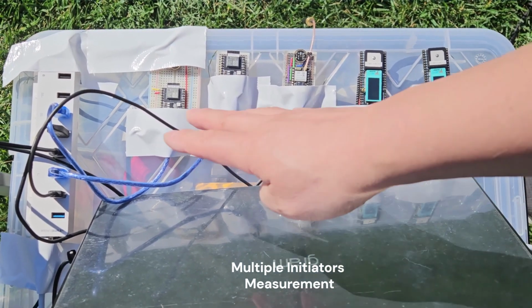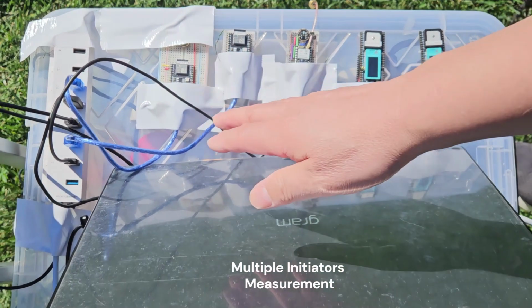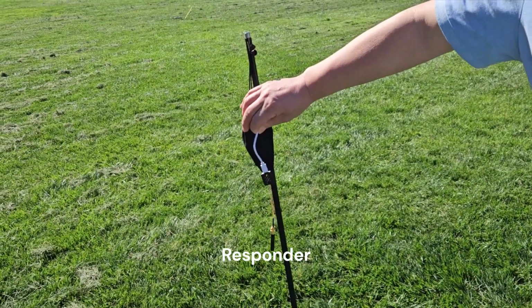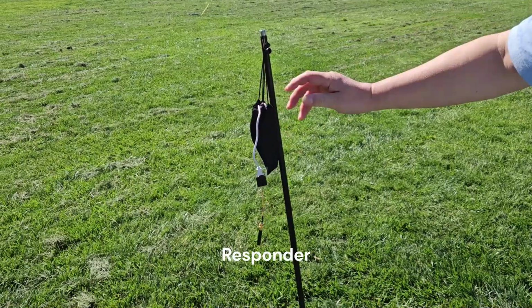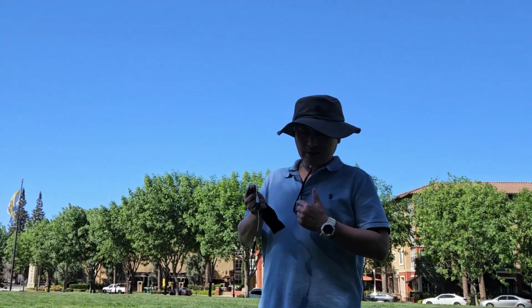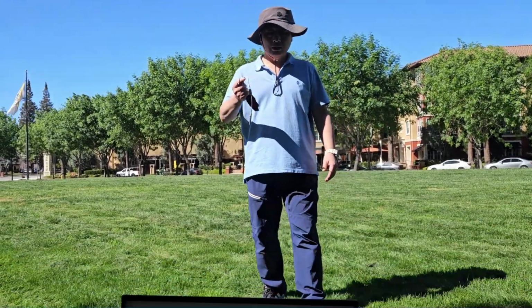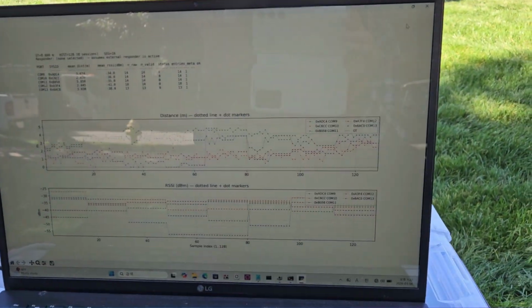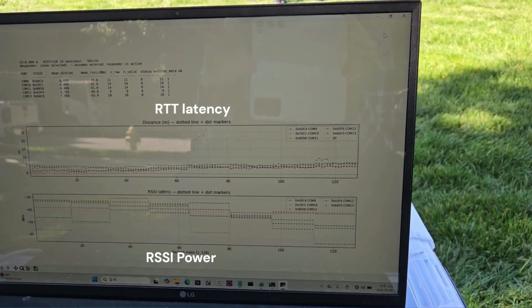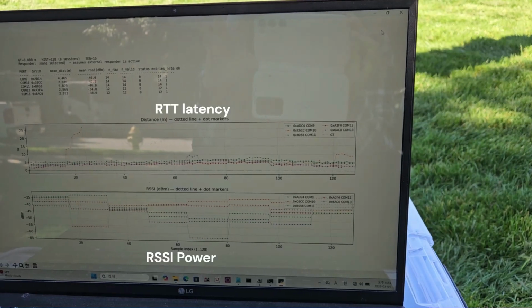I placed them side by side, and from a laptop, I measured the RTT latency one at a time. For the responder, I used a Xiao ESP32-C6 board with an external antenna. Then I moved the responder from 1 meter up to 20 meters. I also tried longer distances, but beyond around 20 meters, the signal became much weaker and reliable measurement was difficult. So for this experiment, I mainly focused on testing the range from 1 meter to 20 meters.